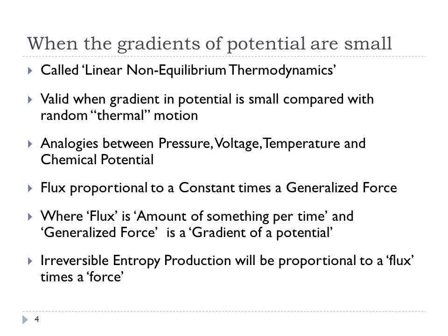What that means is that if you consider the size of the gradient, let's say for a heat exchanger, you have a temperature of T2 or T hot on one side and T cold on the other, and then you've got the distance between them. What we want to know is whether that distance between the two temperatures is large compared to the length scale at which energy is randomized, which is close to the mean free path of particles.